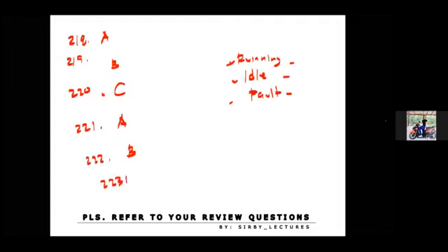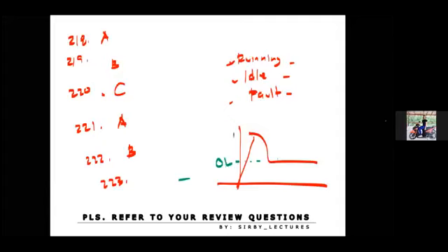Number 223. It is a device in the manual motor starter to check for too much current and open the motor starter circuit before the motor windings become damaged. Okay, so recall in our graph right here, we have this inrush current and then we have this running current. And right here, there's a protection device that's called OL, or overload relays, and right here we have the circuit breakers.